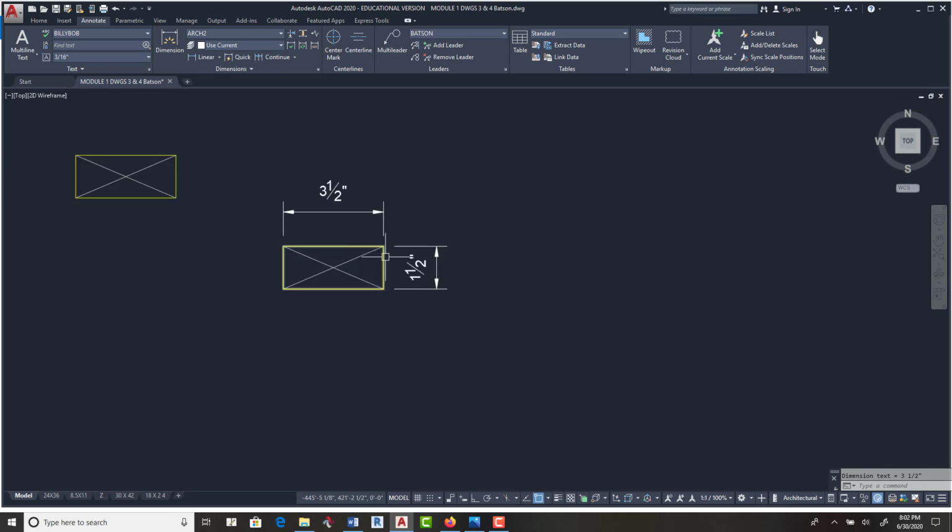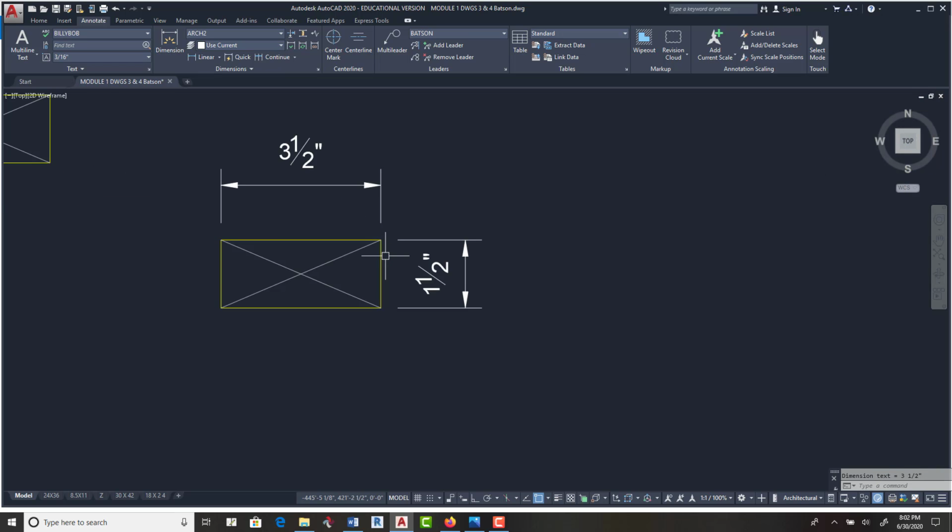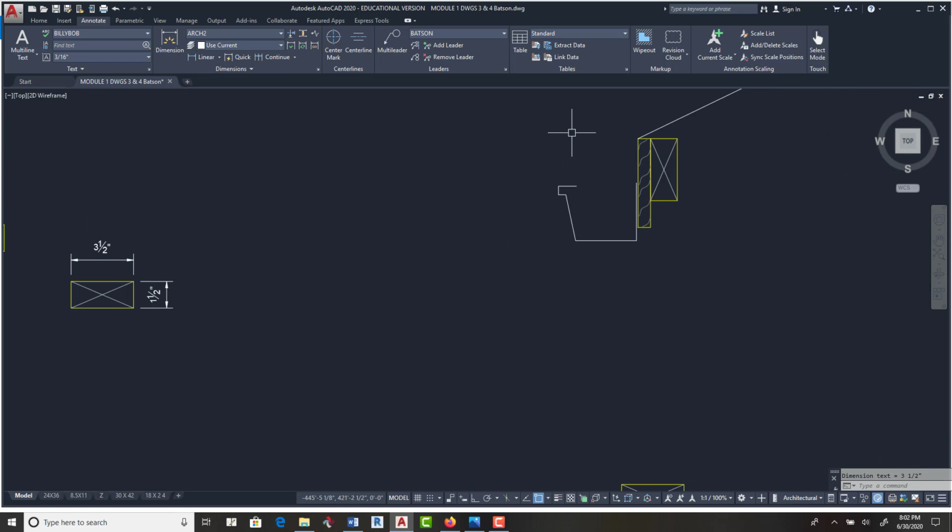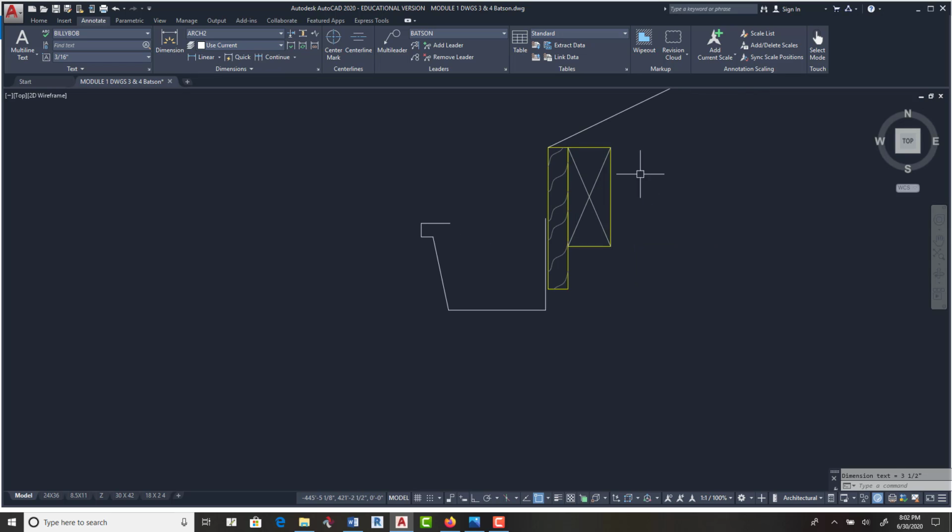Now, to designate finished versus non-finished pieces, let's look at this gutter I've drawn here. This is the 2x4 backing stud, and this is the finished piece of oak. It's very beautiful, and it's going to be nailed or bolted to it. And the gutter can go on attached to the finished piece of wood, because some people don't want a rough sawn piece on the exposed side of their house.